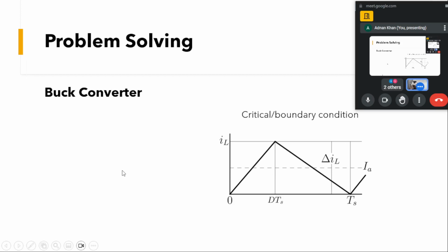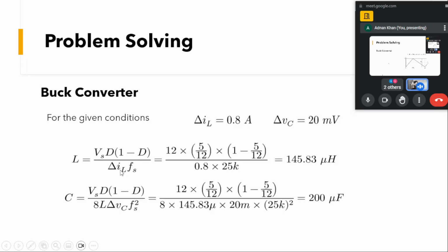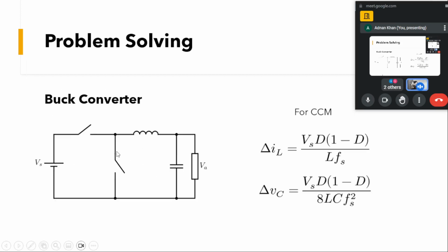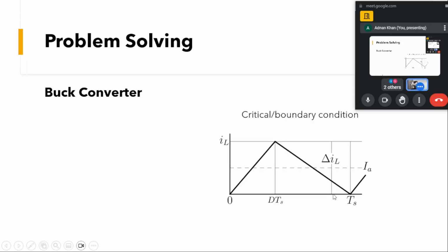After that, in the buck circuitry, the current will become negative and this diode won't be able to conduct that negative current, so the current will be zero for that interval. If our converter operates under those conditions, we say that it operates in DCM, that is discontinuous conduction mode.